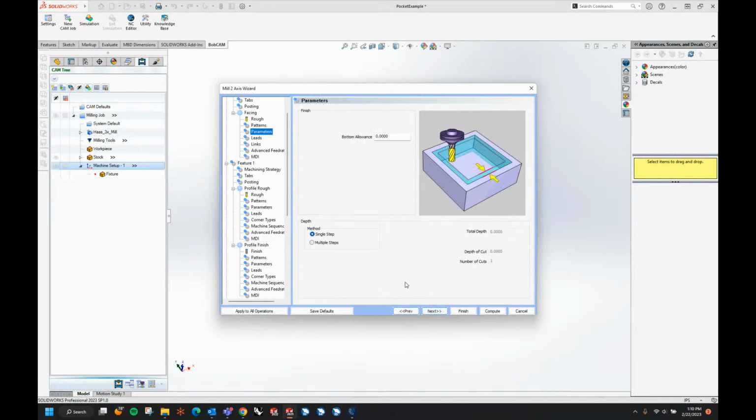See what that looks like. Single depth of cut, I'm not taking anything off. And a lot of times I will actually do this where I will just lower my G54 on my machine or my work offset to accommodate taking off 30, 40, 50 thou off the face of the part, or even just taking off 10 thou. So a lot of times I will program that 0 so that all of the rest of the code is relative to the face of the part that I'm cutting.